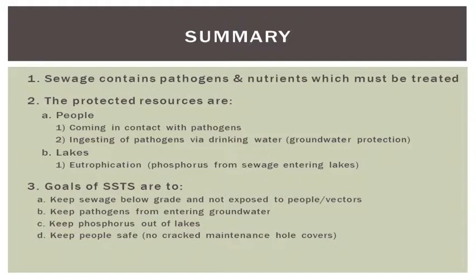So what is the goal of the program? The goal of the SSTS program is, 1, to keep the sewage below grade and not expose sewage to people or to vectors. 2, keep pathogens from entering the groundwater. 3, keep phosphorus out of the lakes. And 4, keep people safe, i.e. no cracked tanks or any sort of electrical hazards if you have electrical devices associated with your system.